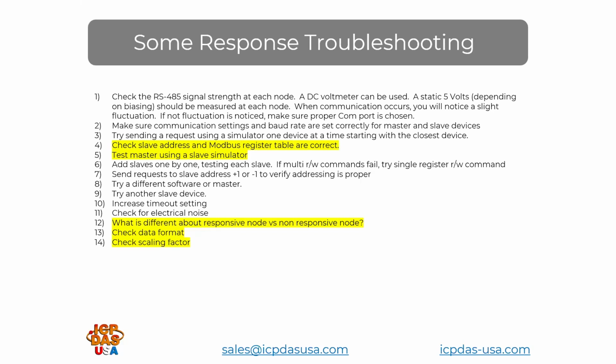You could always test the master using a slave simulator. That's one very good technique to make sure that you're pulling the right register, and if you need to, you can use a master simulator to test your slave devices to make sure they're responding correctly. Towards the bottom, what is different about the responsive nodes versus non-responsive nodes? That's always a common question I ask, because it will oftentimes